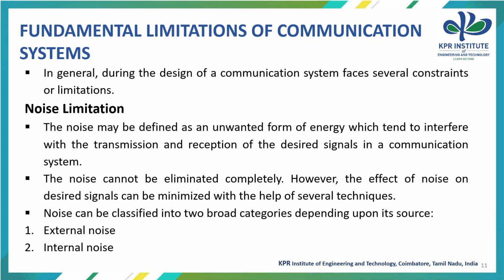First, let us see what is noise limitation. The noise may be defined as an unwanted form of energy which tends to interfere with the transmission and reception of the desired signals of the communication system. The noise cannot be eliminated completely. However, the effect of noise on the desired signal can be minimized with the help of several techniques. Noise can be classified into two broad categories depending upon its sources. One is external noise, another one is internal noise.